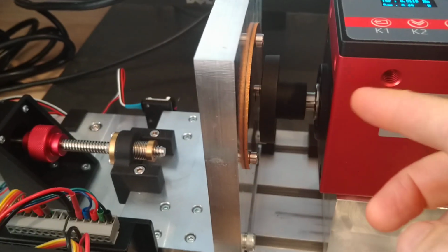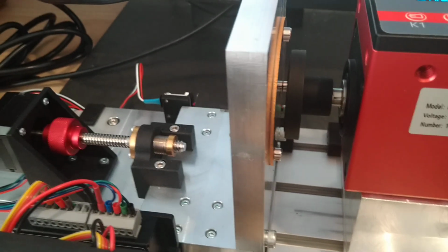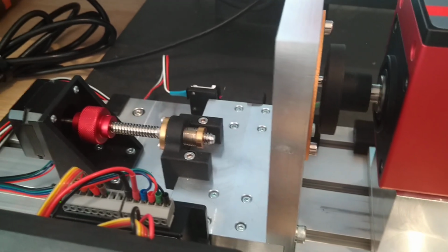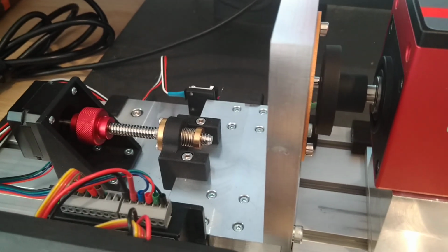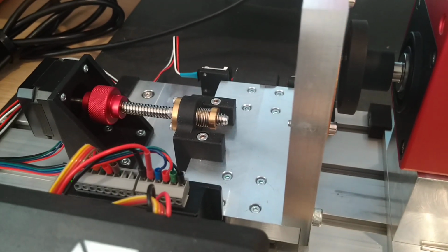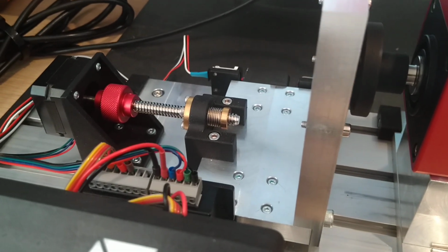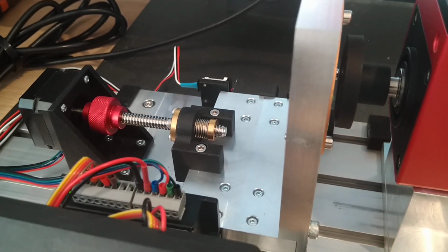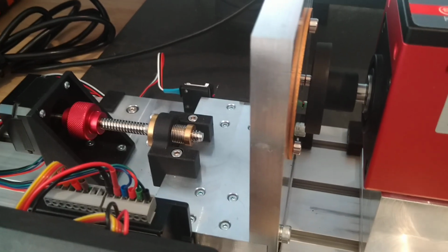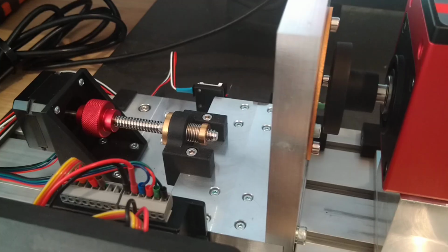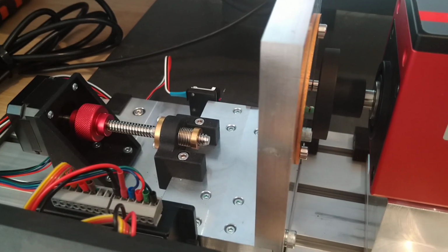We have tested this control algorithm with this very small loading permanent magnet rotor, of approximately 50 millimeters in diameter. But we also tested it with 80 millimeters rotors and 110 millimeters rotors, but also 160 millimeters rotors that weigh in the neighborhood of 3 kilograms, really large, and being able to output 20-25 Newton meters.